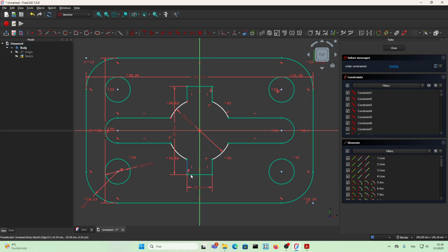Now, if you are not able to see what's missing, you can always try like this. But remember, when you move it, you can see. Now I want to understand what's happened. Is this constrained? See, I clicked on it and I moved it, and it moves. It's not constrained in this direction. So what do I do? Let's move it, for example, to here.